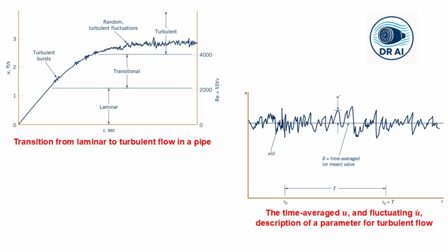At first, it's laminar, smooth, and orderly. As the Reynolds number passes about 2100, the flow enters a transitional phase. You start to see intermittent bursts of irregularity, spots of turbulence appear, and then disappear. The flow flickers between order and chaos. It's unpredictable. And finally, as the Reynolds number exceeds about 4000, the flow becomes fully turbulent. The entire pipe is filled with that chaotic random motion. This randomness is the defining feature of turbulence.